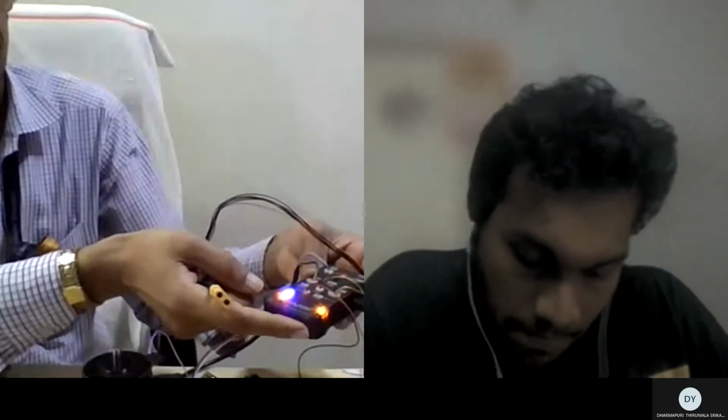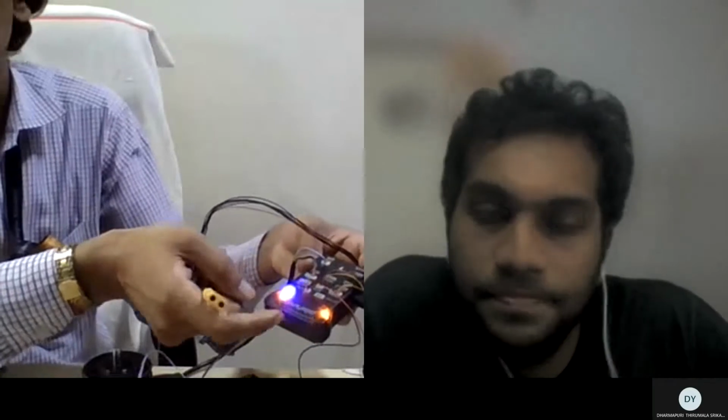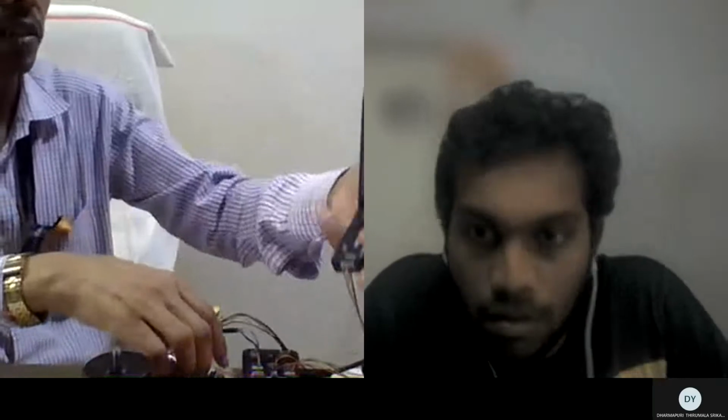So for powering this, you need some ESC, a speed controller, or maybe a current sensor connector connected with this, which can power this rail. Then only you can get the signal, and this is a very good idea. Otherwise sometimes this damages the whole system. Many times a student will forget to power the rail, and they will tell me, sir, the output is not coming.